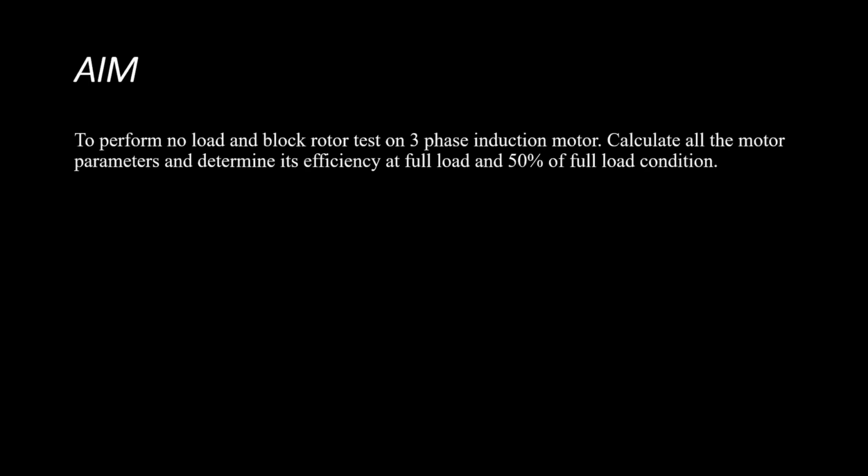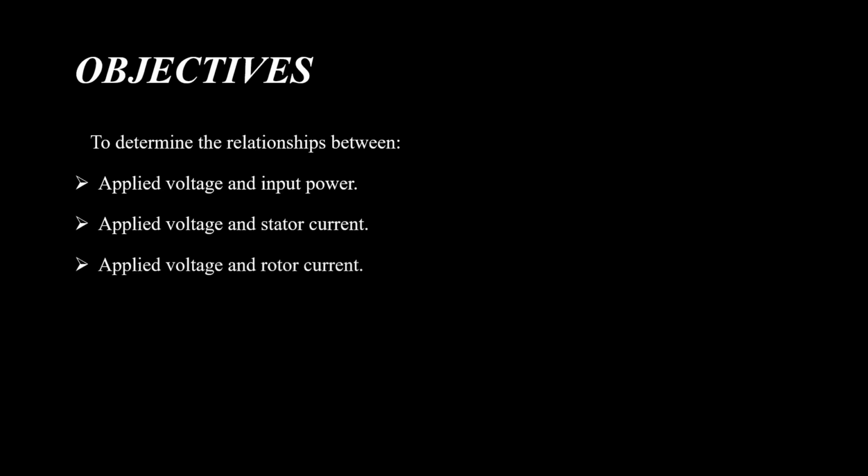The aim of this practical is to perform the no-load and blocked rotor tests on a three-phase induction motor, calculate all the motor parameters, and determine its efficiency at full load and 50% of full load condition. The objective of the practical is to determine the relationship between applied voltage and input power, applied voltage and stator current, applied voltage and rotor current, and applied voltage and the current.